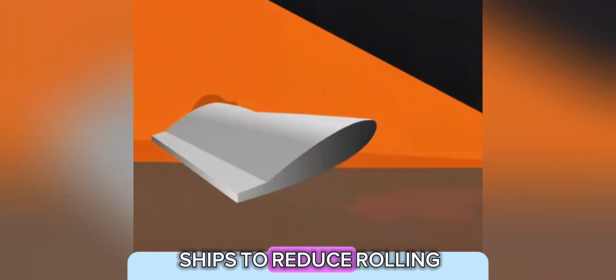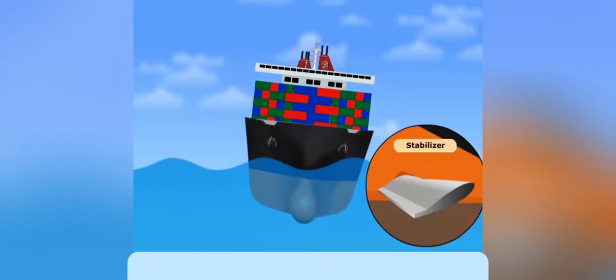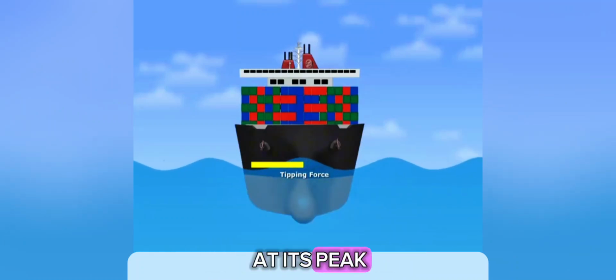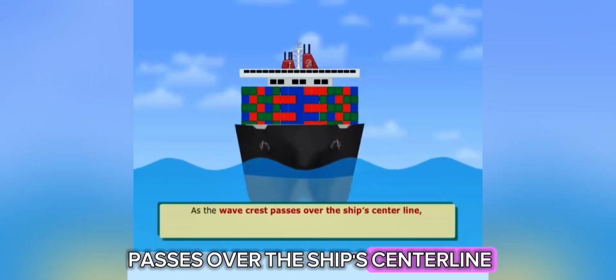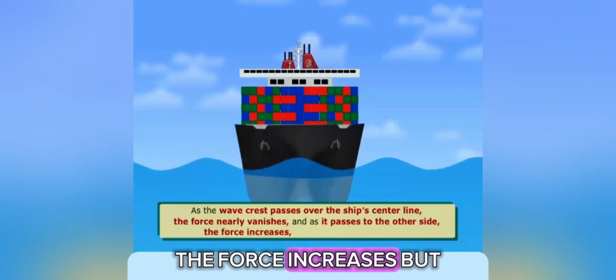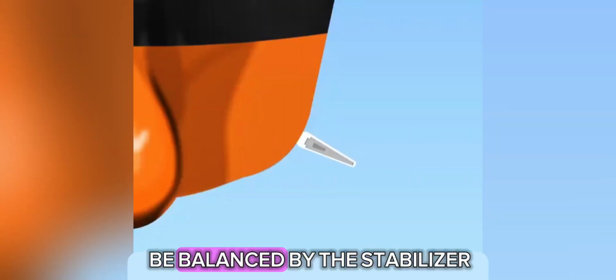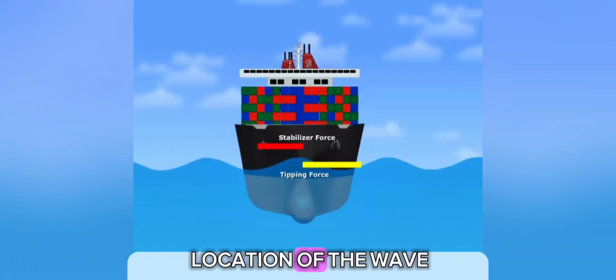Stabilizers are used on ships to reduce rolling. A stabilizer's purpose is to counteract the force of a wave. When the crest of the wave hits one side of the ship, the tipping force is at its peak. As the wave crest passes over the ship's center line, the force nearly vanishes, and as it passes to the other side, the force increases, but in the other direction. All of this must be balanced by the stabilizer. It must be able to adjust the amount of force it generates based on the exact location of the wave.